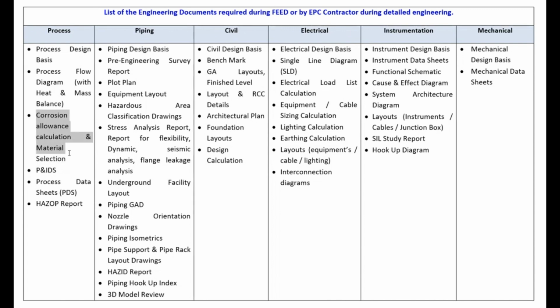There is a report actually. This report is sometimes developed by the process engineer or with the support of a metallurgy engineer, because you have to calculate the corrosion allowances based on pressure and temperature conditions. It's not only the fluid property, whether it is sour or sweet. Sometimes when the temperature increases, if we are dealing with high pressure and temperature conditions, specifically for the compressor discharge line, a small ppm of H2S is more corrosive at high temperature. That's why the metallurgy selection has to be done, and for that there is a calculation for corrosion rates and material selection conditions.